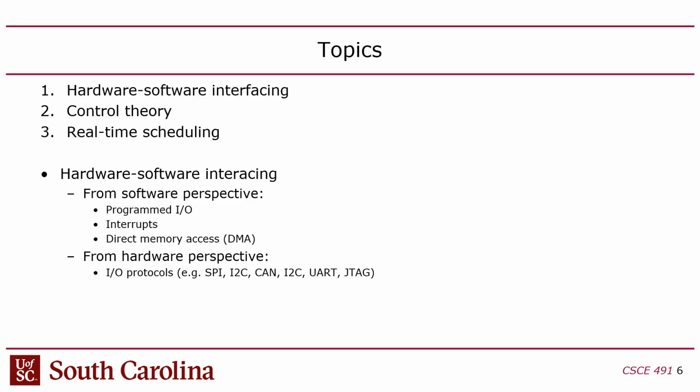Now there is a free RTOS that runs on these boards, but it doesn't do the really important work of a real-time operating system, which is to guarantee that performance constraints are met. In other words, you can't submit to it a list of tasks and ask it if it's feasible. It won't tell you that. It'll invoke the tasks, but it won't tell you, hey man, don't put this in the cruise control system because this is not going to work. There's too much work. Your utilization is above 100%. I can't do it. It's too dumb to do that.